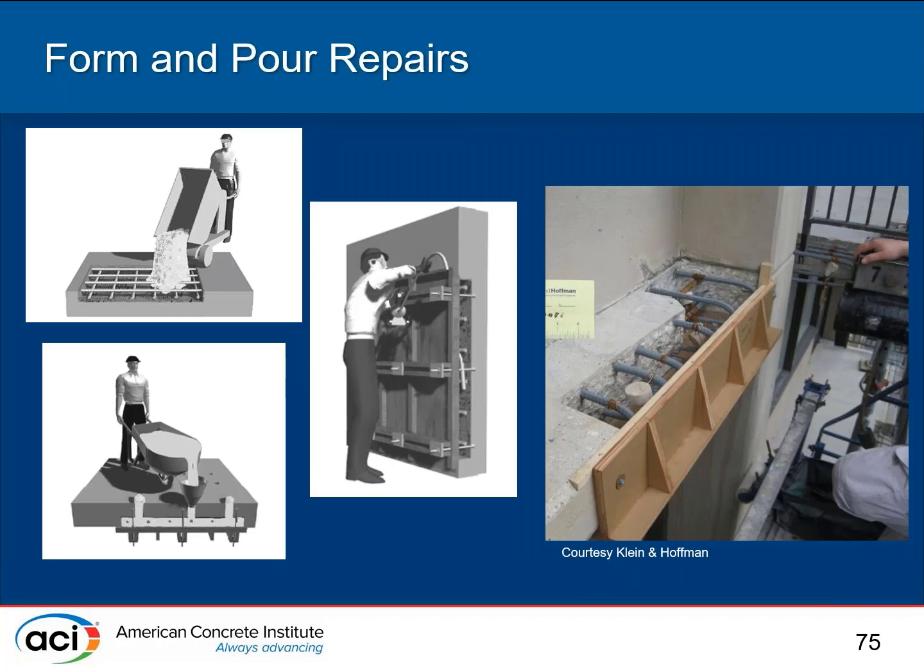First one is the one that's most similar to new design, to new construction. You're basically getting your concrete from wherever your supplier is and pouring it in and vibrating it and finishing it and all that kind of thing. Similar type of formwork may be necessary, though sometimes formwork isn't needed if your partial depth repair will contain the entire concrete. Similar type of curing, similar type of stuff, but something that should be very familiar to anyone that's been on a concrete construction project. It is in many ways not very conceptually different than new design.